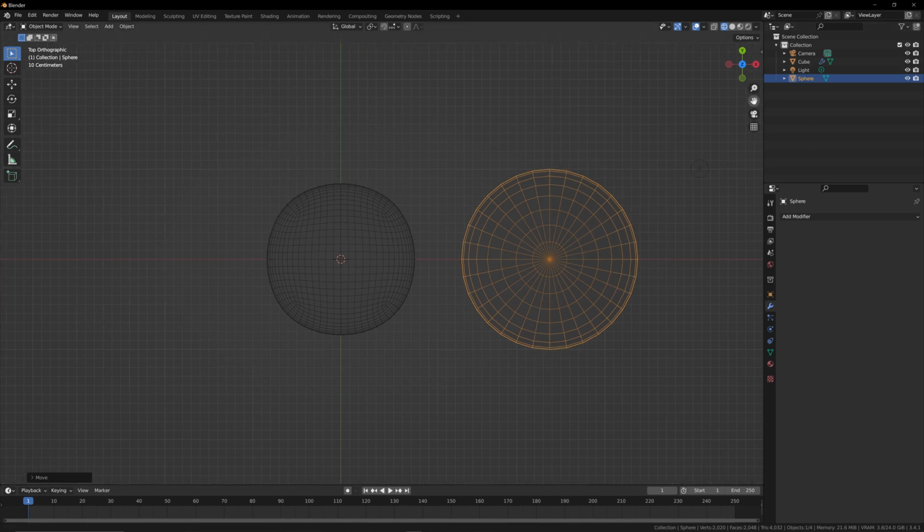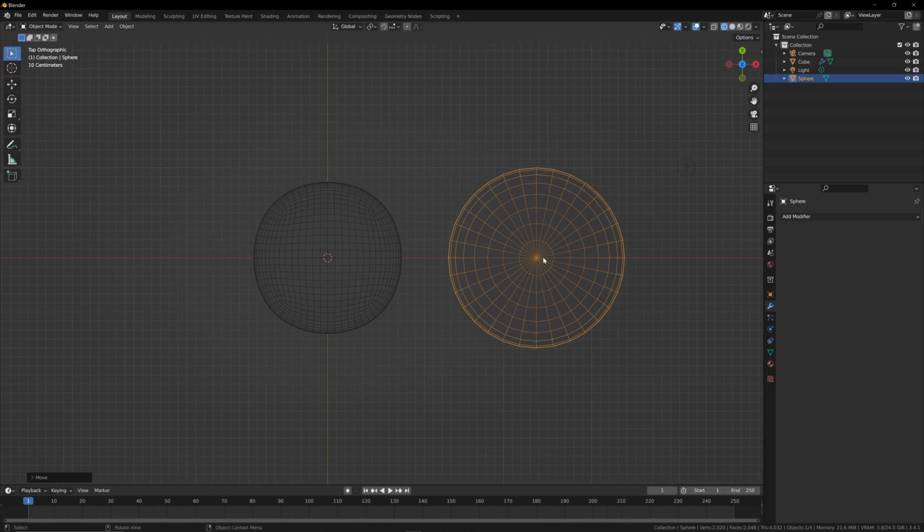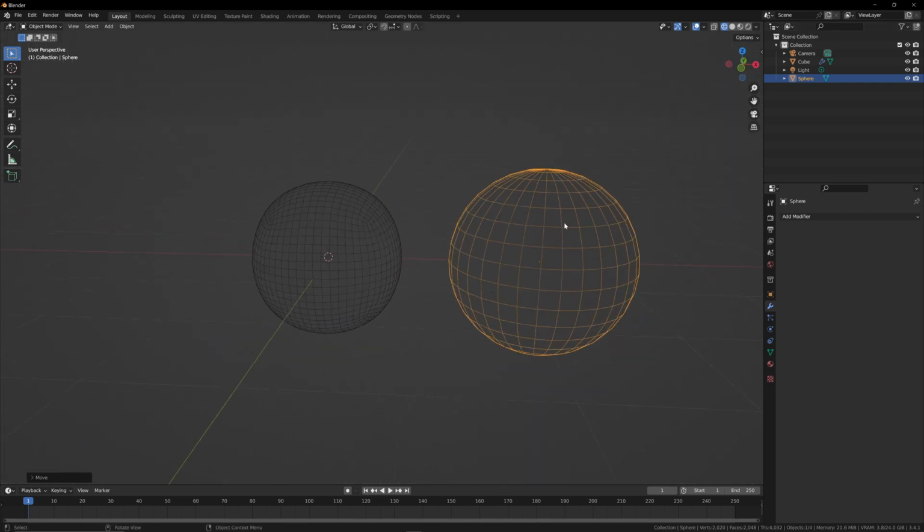So if we look at this from the top, with the spherical one, our texture is going to be pinched into this kind of little point here because of how these faces are projected. Whereas with the subdivided cube, our topology is kind of flat and consistent across anything. There's no pinching. The same from the side and the bottom. That's why I'm going to use the cube in this instance and not just click and add a sphere. So just to explain that if you are wondering.